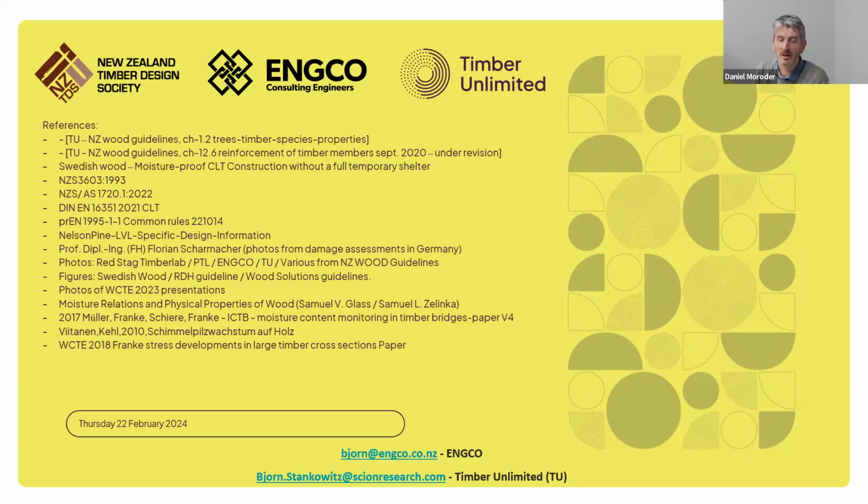Two follow-up questions on that, Bjørn. Have you ever seen a moisture content increase if you use previously punched holes? For example, if there's any surface water trapped in the holes, is that something you have seen or something you would be aware of? I haven't seen it myself, and I think once you see actual water squeezing out of a probe hole, you should ask yourself, is it still the right location to measure, or should I just maybe move it slightly over to the side? So common sense revealing, and I think you will see that straight away. There might be a difference if you measure the same hole, there's no water coming out. So look, I would move over to another hole if possible.